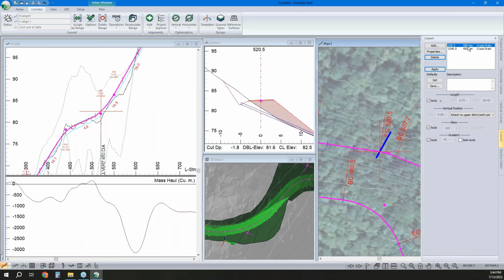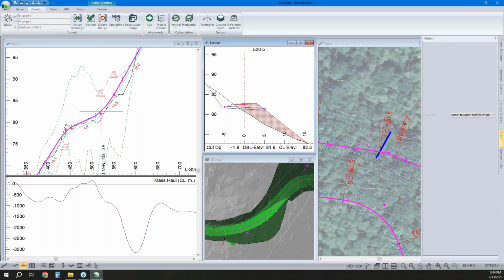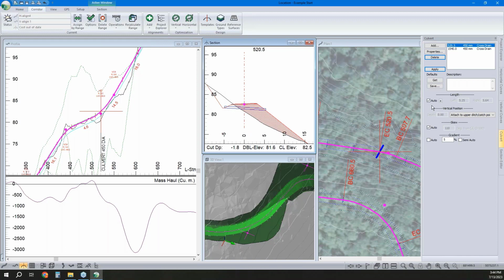So we'll see here that I've got that set to auto. Let's change that to something like that. So here, auto is sizing my pipe. And I've got this like 5 1/4 and 5.64. So that's not going to round it up to any particular length, but we can turn that off once we're close to being done and say, well, I want to have this incremented in closest half meter, and there we can set that. So yes and no.